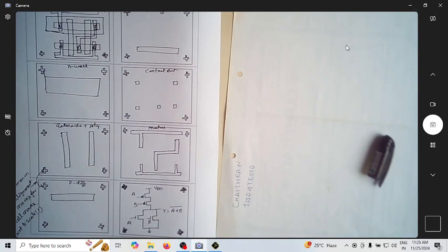So to realize this NOR gate, which results in this overall layout comprising all the masks, we are writing separate masks for creating the N-well, polysilicon, and of course the gate structure. I have shown how the thin oxide should be visible.